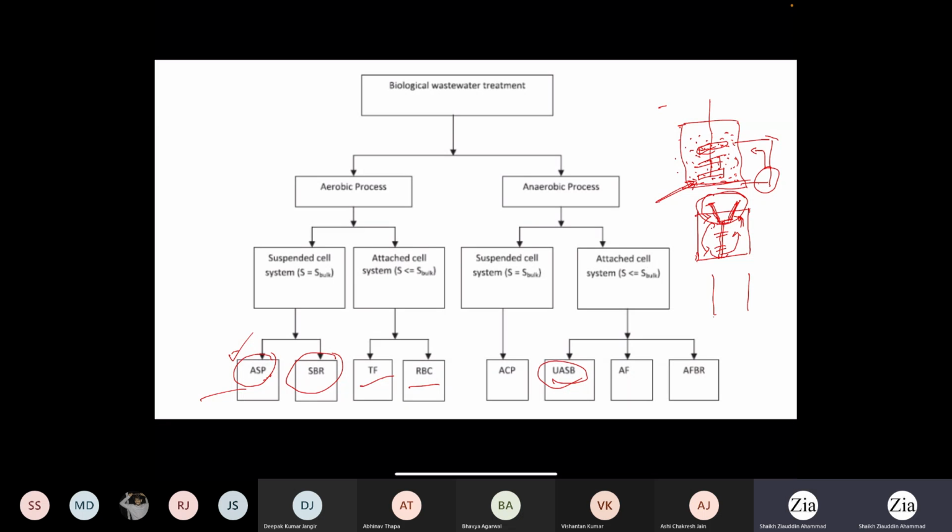Another option is to use a sparger at the bottom, a fine sparger that could be made up of membrane material, ceramic membrane, rubber membrane, or you can have a simple nozzle or jet or different membranes. And then you create air bubbles. Whenever the air bubbles move up, they'll create the churning motion, so it will not allow the solid to settle at the bottom.